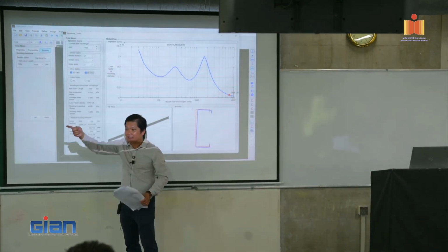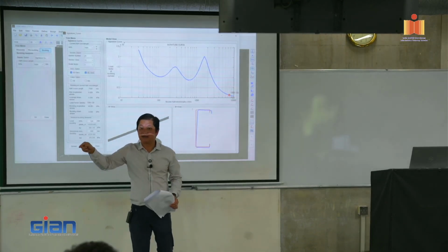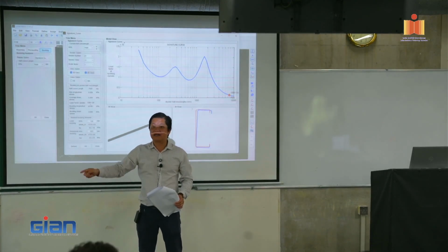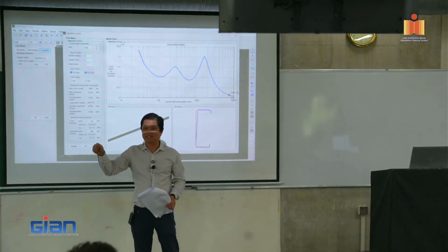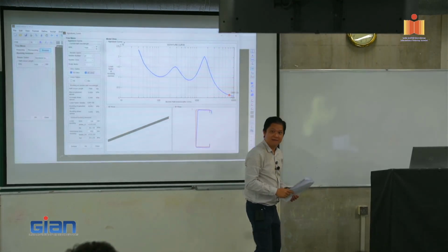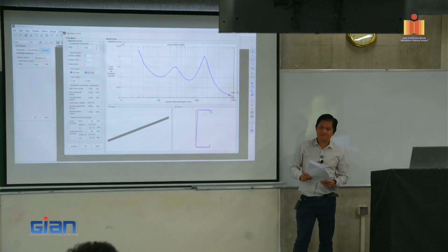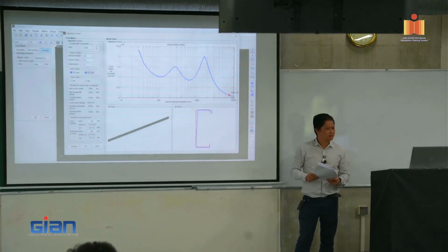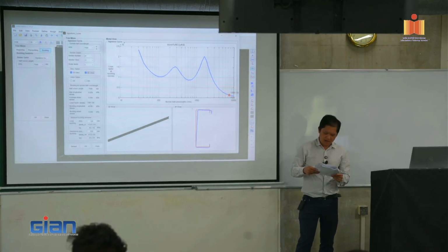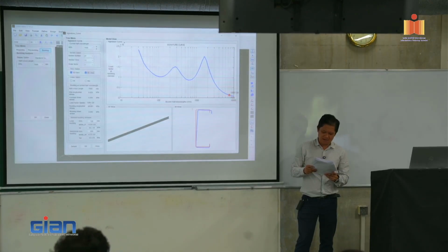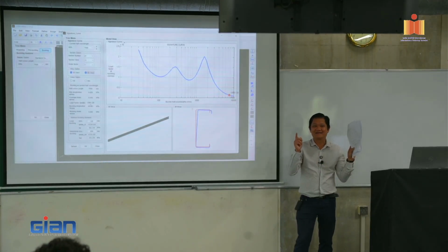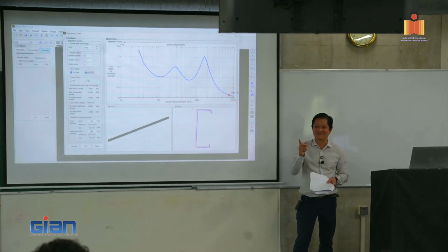You times with 1,000, you got Newton millimeter, and you divide it by 1,000, you got kilonewton millimeter, and divided another 1,000, you got kilonewton meter. 1.3, yeah? Here it will be 1.3. Yeah, and your calculation says 5.8. Something not right? Oh, yeah, I know why. Because in here, you put the bracing in the middle. That's a good one.